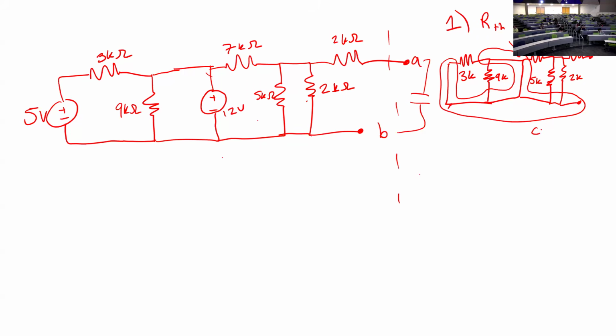All right. So the big thing that I want to note here is I have these 2 resistors that are connecting to the same node on both sides. So if I have a wire on both sides of a resistor, how much current am I going to get? If my potential is the exact same on both sides, if the height is the same on both sides, is anything going to want to flow down a slide like a resistor? No. So we're not going to get any current. These things don't matter. I can redraw this.